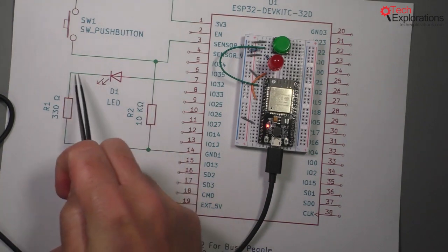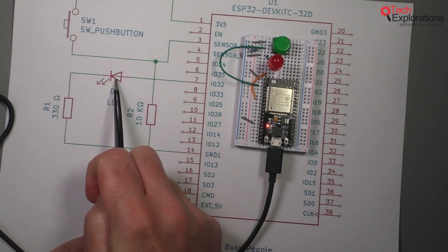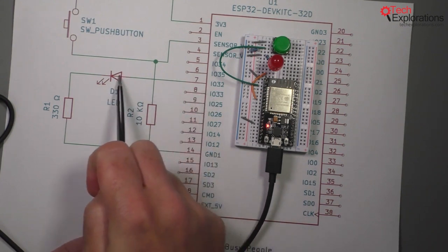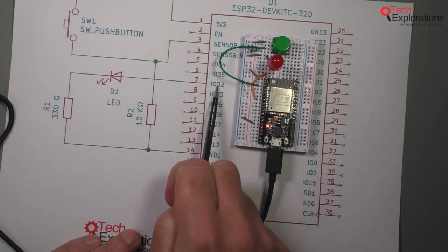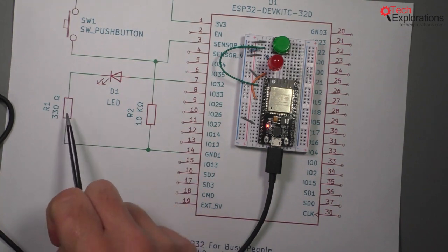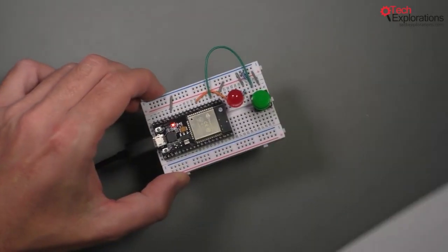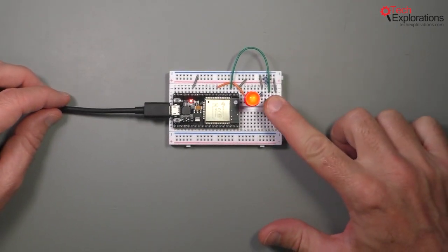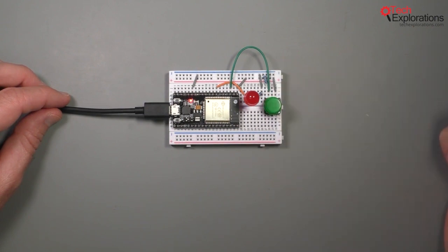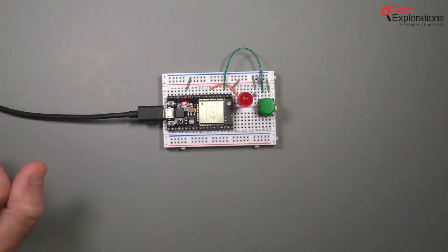And then for the LED, the situation is very simple. We've got a 330 ohm current limiting resistor. Via it, the LED is connected to GPIO 32 in series with a resistor, and then the cathode of the LED goes to ground. Alright, so I've got the sketch running on my ESP32. I press the button, the LED goes on, let it go, depressed, the LED goes off. It's exactly the kind of wiring that you would do with the Arduino.